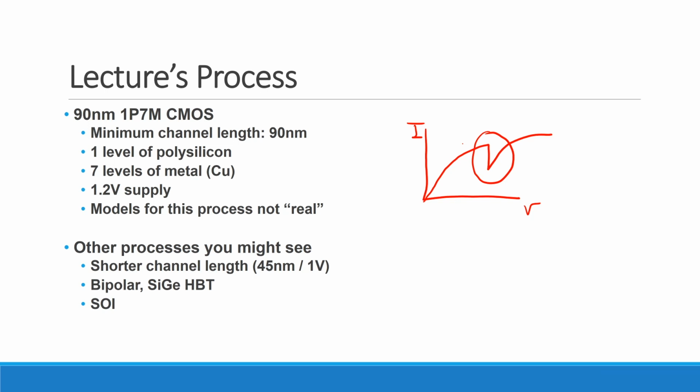So the warning is, when you're doing something with your circuit and you're getting results that look like garbage to you, that probably means it's garbage. Maybe you don't understand what's going on, but most likely it's garbage, because if it's too good to be true, it's probably too good to be true. Bottom line, don't just run SPICE and trust what it says. Actually think about what you're doing.